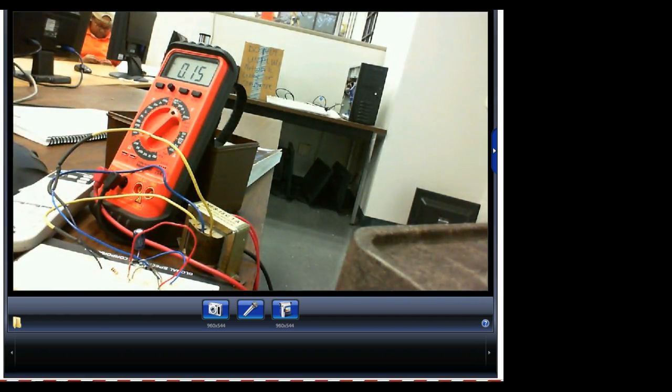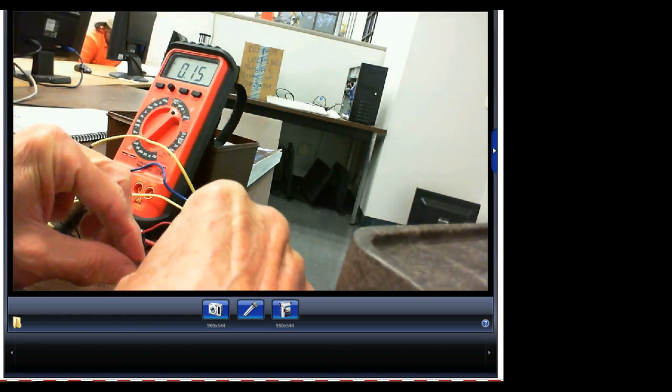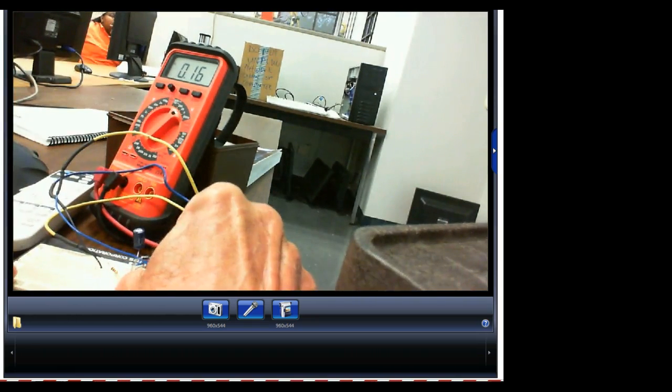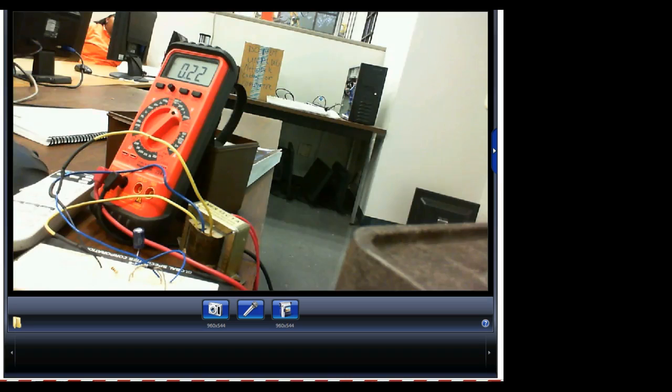If the diode shorts, we get AC across the load, right? You understand? If the diode opens, we get nothing across the load. And how do we check a diode? What do we use to check a diode? How do I check if the diode's good or bad? Well, we can turn the power off. So we never put an ohm meter in. This is another thing we got through talking about. Not supposed to. Well, we do check with power all the time. But what we're going to use on our meter, we never check with the power. So how do we check a diode?